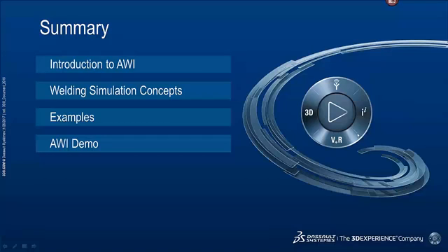The basic feature of any material activation method should be that you can't have a jump in stress when the material goes from inactive to active, because what happens in general is that when the material is inactive, it is going along for the ride, but it does have a certain amount of elastic strains in it, and so a certain magnitude of stress in it when it is active.